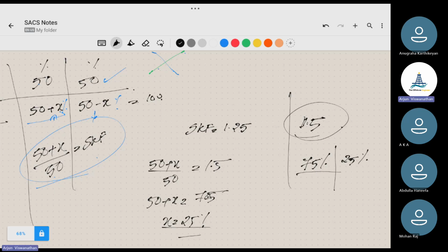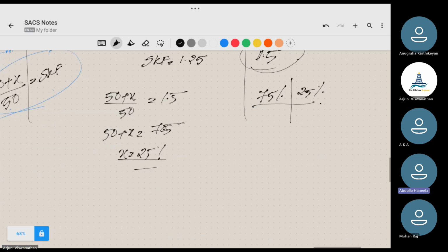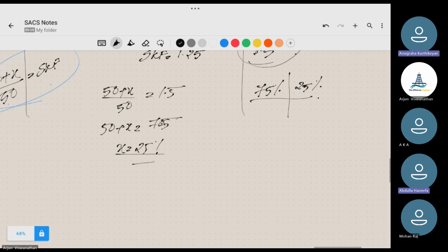Are you clear? If there is an asymmetric structure, then this skew factor is applicable. Whenever we have these 4-point lifts, skew factor will be applicable. We need to do skew. That is very important. If we don't do skew, that means we are missing something.